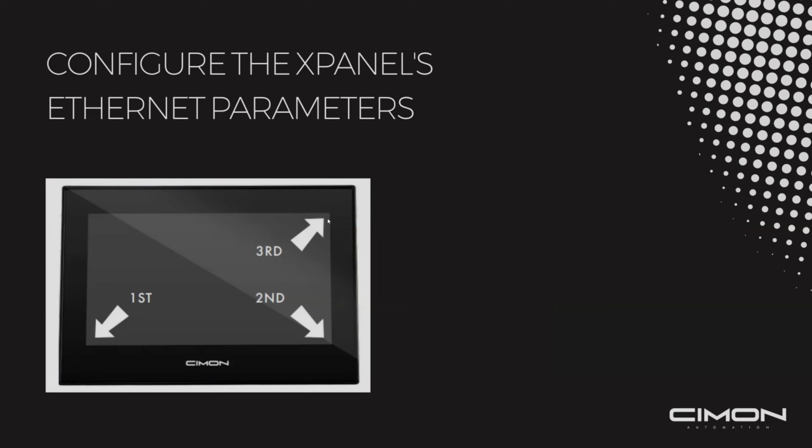So let's not spend too much time on that, but that is how you get to the Ethernet parameters. And once you get to those Ethernet parameters, you'll notice that there's two LAN IPs that you can allocate to the X panel. So that means that our X panels come equipped with two Ethernet ports, and they're gigabit. There's a USB port as well, a USB mini B port that will be treated as an Ethernet interface when it's connected to your computer. That way you don't need any type of third-party software when connecting to the X panel with the software. It'll just say USB. You might have seen that when I popped open the network connection tool there. It said USB instead of an IP address. So we treat the USB as an Ethernet port.